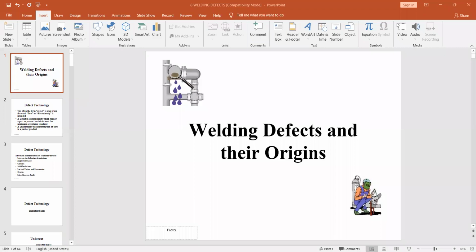So just consider we are doing welding, and the welding generally we are doing as per WPS. The WPS will give the guidelines for what is the current requirement, current range, voltage range, traveling speed, interpass temperature, preheat temperature. So these 4-5 parameters are very important.